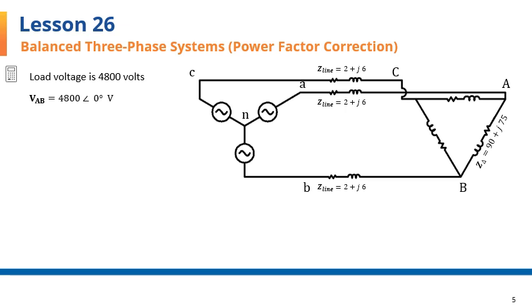I will use power triangles for the purpose of determining the size of the capacitors that will achieve a load power factor of 0.95. Power triangles were covered in lesson 17. To start, I'm going to need single-phase load powers of the system before installation of the capacitors, and we'll copy those from lesson 25B to the next slide.